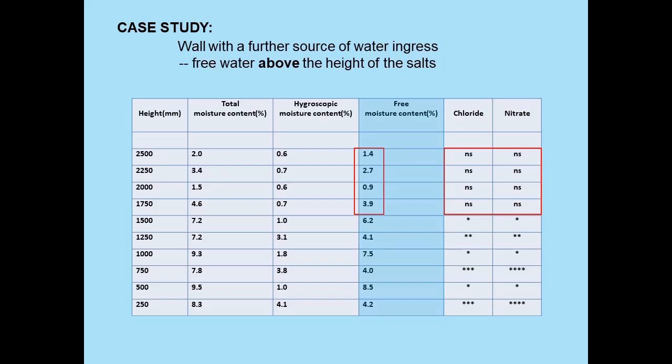And when examined outside, there was a small box fitted to the wall. Couldn't see any water run marks from it, but clearly when it was raining, water was collecting behind and penetrating the wall. So in this case, we don't exactly know how much water was coming from the rising damp and how much was coming from the water penetration, because we don't know exactly how much water at the lower level was penetrating or running down the wall or into the wall.